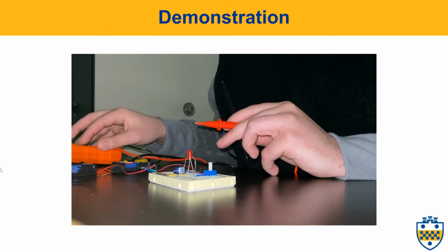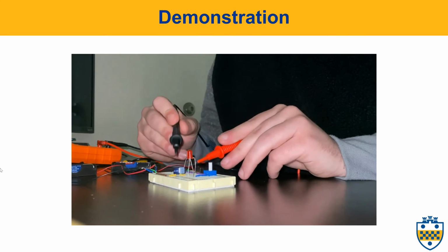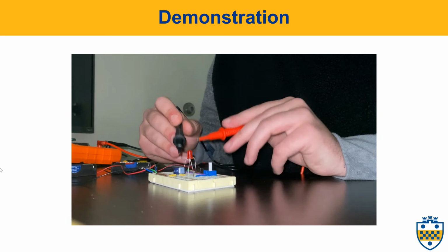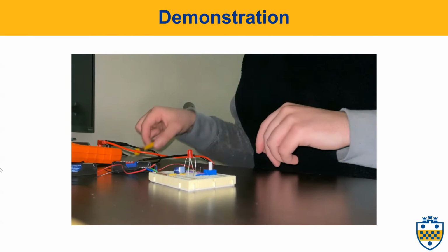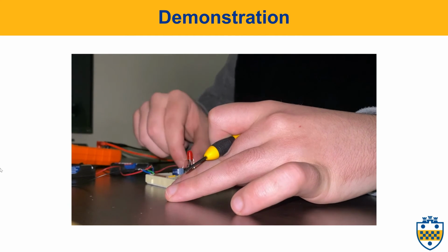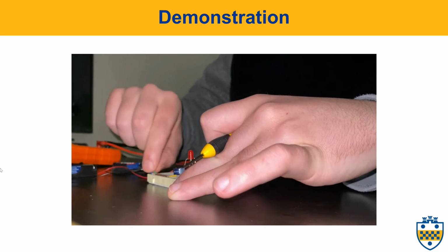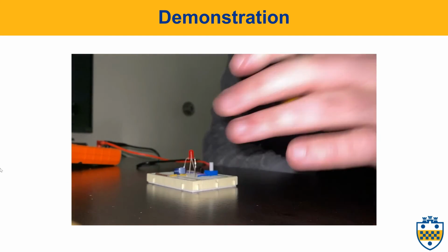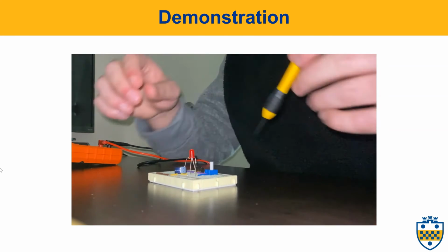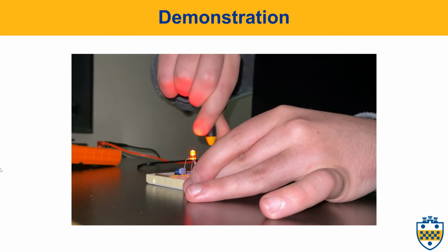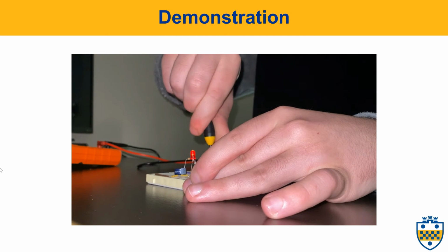We now will flip the switch, and it will be shown the light being able to be controlled by the potentiometer, as you can see it getting dimmer and brighter. The switch is now flipped. The battery source is now unplugged. As you can see, it begins dim with a resistance of 10 kilo ohms on the potentiometer. And now when the potentiometer is turned, you can see the light getting brighter.